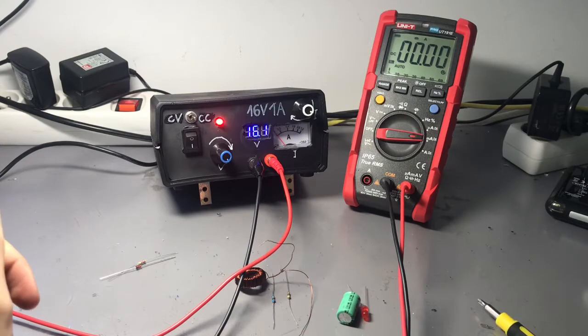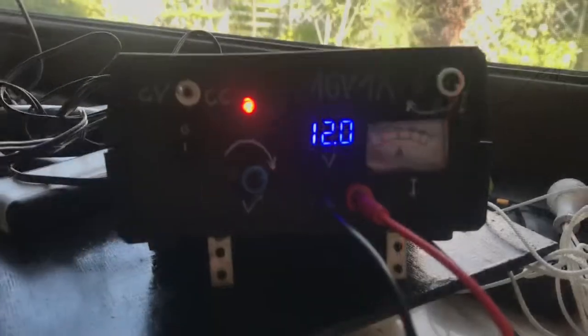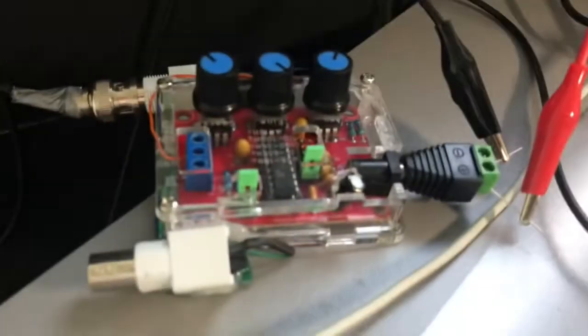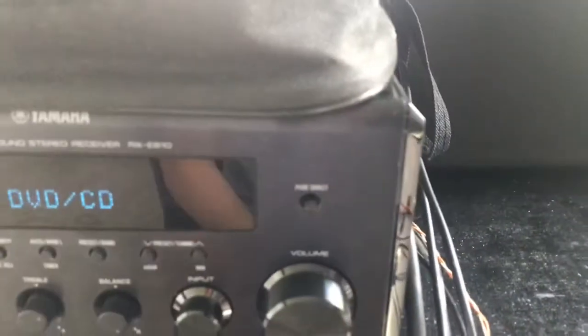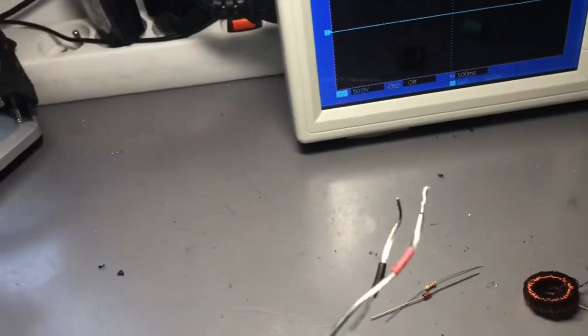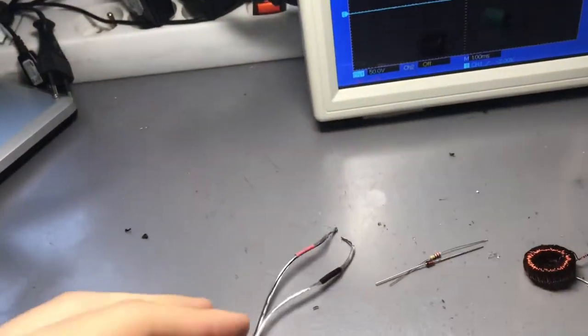Let's right now put here a scope and a function generator. Okay, so in order to make our signal appear on the scope here, I have set my power supply to 12 volts, then the power is connected to the function generator, and the function generator goes to the amplifier, and then we have the wire from the amplifier here with our triangle wave for measurement.